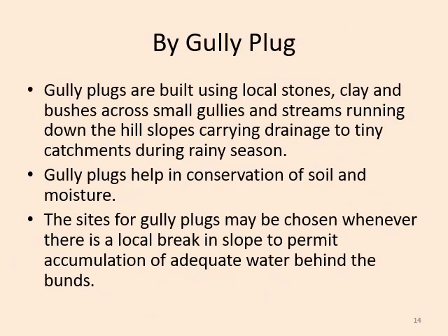Now we are coming to gully plug for rural areas. Gully plugs are built using local stones, clay and bushes across small gullies and streams running down the hill slopes, carrying drainage to tiny catchment areas during rainy season.